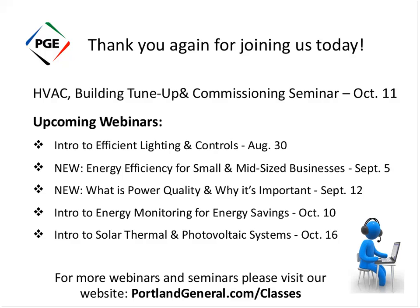Yeah, that's a good question. I think one of the key things is identifying where your meters are and what equipment those meters serve. For example, in PGE territory, you can get 3 bills, but 2 of your bills may be for exterior lighting that really isn't metered, and that use isn't going to change over the course of the year. It's billed out at a set rate, and that billing is not going to change. So if you've got multiple meters, make sure that they are serving loads within your building that you can then discern where that power is going to. That's an opportunity to kind of reduce your workload.